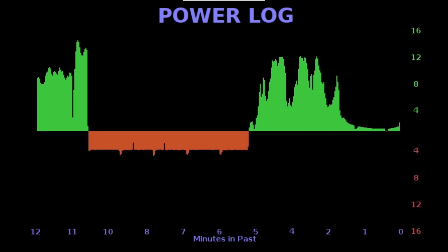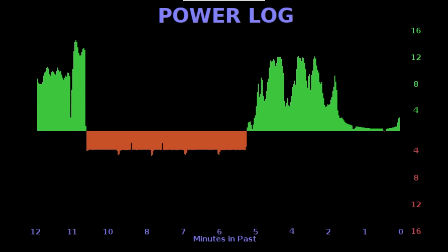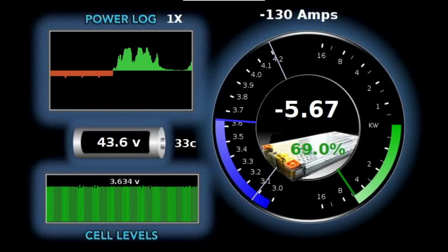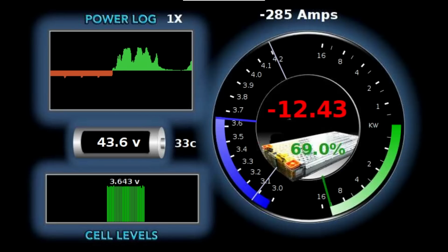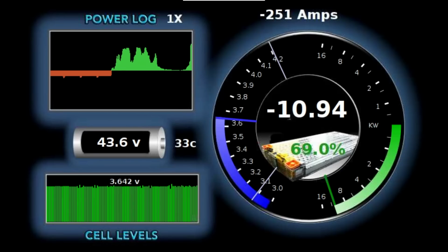But if you get up to 14, 15 kilowatts, the inverter did something that threw off our solar edges, and they simply went away. Let's see if it does it again. I got some sudden sunshine here, and we're up at 10 or 11, 248 amps. Let's see what transpires, see if we can get it to trip again.